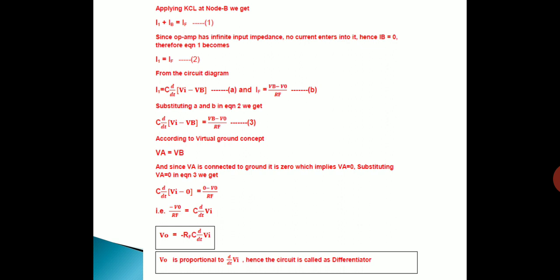Now if you substitute these two currents, I1 and IF, in equation 2, we get, as you can see here on the screen, C into d by dt of Vi minus Vb equal to Vb minus V0 by RF. That is equation 3. Now we have to simplify this equation 3 and get the output equation V0 in terms of Vi. But here in equation 3 we have Vb, the node potential of node B. Now how to get this node potential of node B? That's where the important concept in op amp called the virtual ground concept comes into the picture.